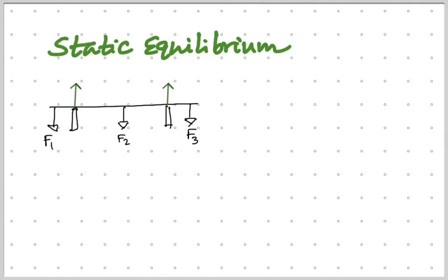Okay, so here you have this supported at 2 points, 2 supports here, 1, 2. These are the reactions at the supports, and you have 3 forces. And this force may be the mass of that or the weight of that beam. Now that's something that students forget. Do not forget. If I say it's a uniform beam, its center of gravity is exactly at the center, so don't forget that.